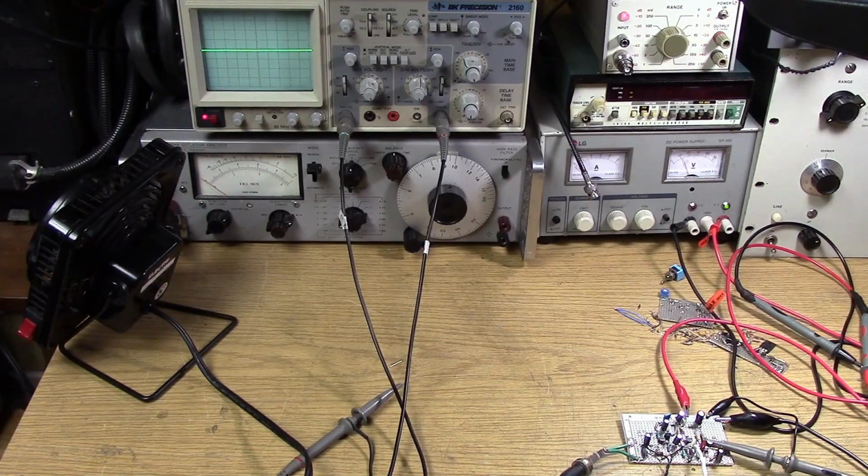So in order to make the negative peak clipper work, we have to have enough amplitude to turn the diodes on, which means we're going to need a couple volts of audio. Now the preamp can almost do that. It's lacking a little bit of gain. And the other problem we have is the phase splitter that we selected, being a transistor type, is sharing the load of the 12 volts on the circuit. And I'd rather not run everything at full output, full gain.